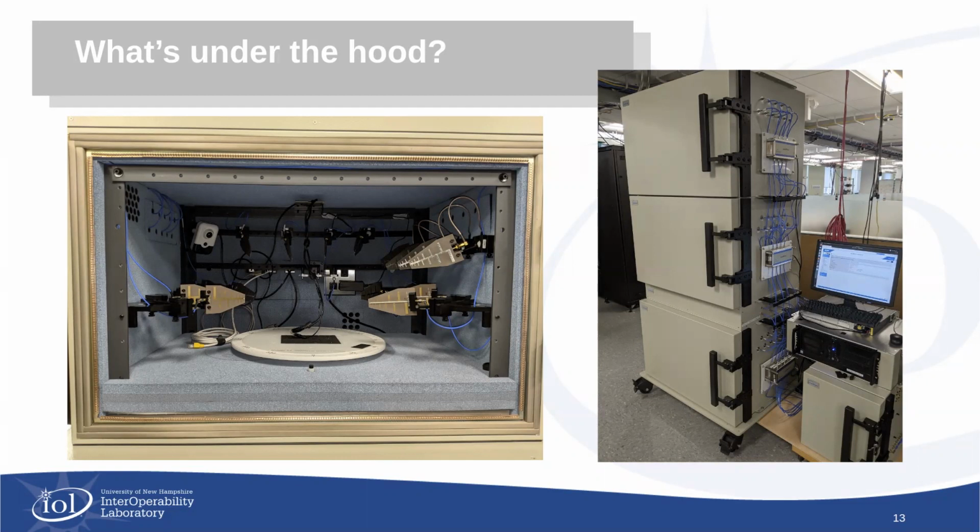That meets the requirements outlined in 398 for some of the MU-MIMO testing, ensuring you have some level of spatial divergence, with stations appearing to come from different incident angles with different RF paths. You also get a different RF path as it couples into the antennas inside the device.